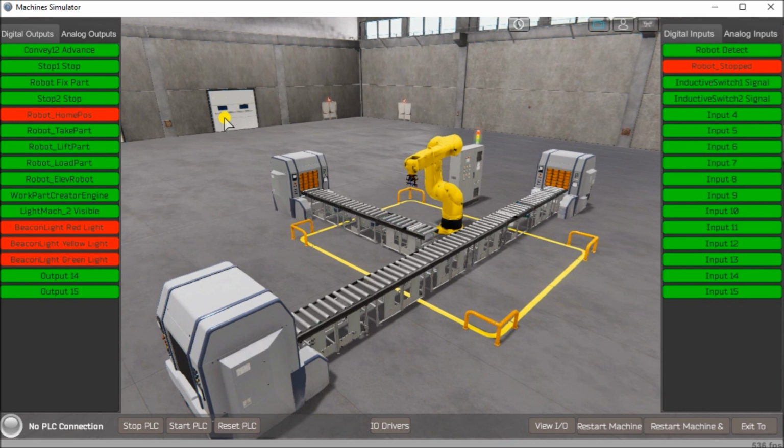Next is step 3 of our EasyPLC Robot Cell, which is develop the logical sequence of operation. Now this is where you're going to spend most of your time. And a flowchart or sequence table is used to fully understand the process that needs to be controlled. It must also answer things like what happens when electrical power and/or the pneumatic power or air is lost, what happens when the inputs and outputs fail, do we need redundancy? Questions like that must be answered.